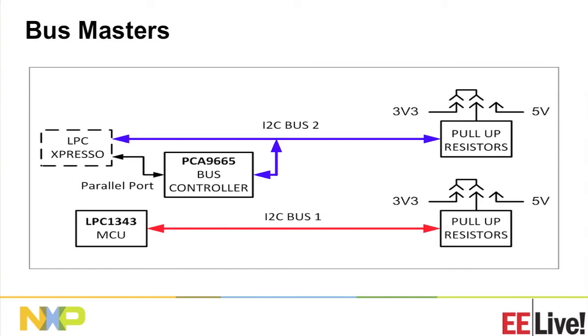We also have in our product line bus controllers. The idea of these is very simple. You take a microcontroller that speaks parallel port signals, and you let this chip do the heavy lifting of creating the clock and timing for the I2C bus. By using this device, your processor, or whatever it is you're using that wants to drive the bus, doesn't have to understand the timing or the signal format for I2C. We do it for you.